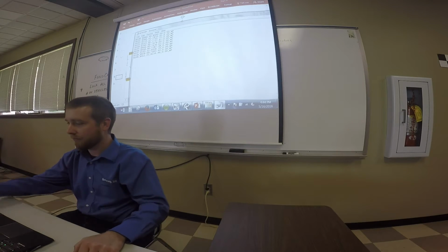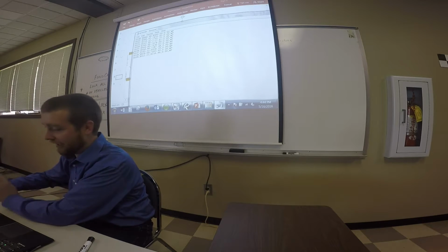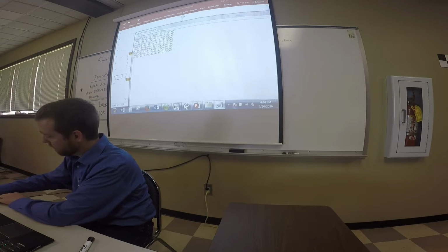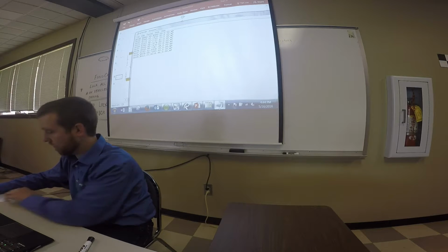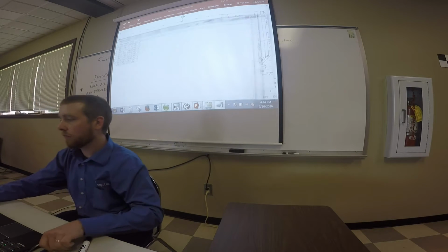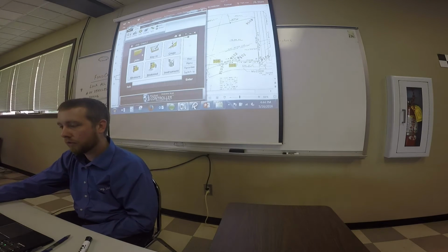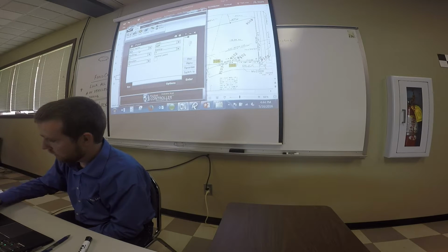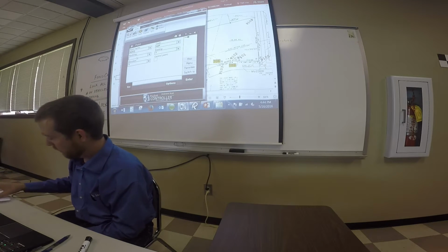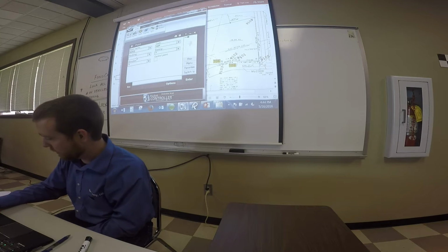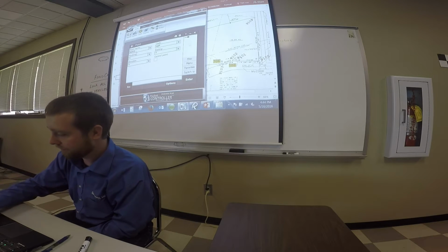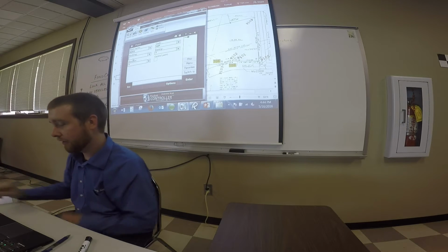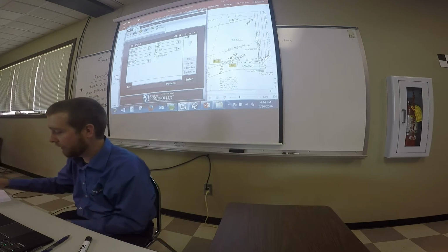And the reason you can enter just one is because he hasn't done a rotation. I have not done a rotation yet. It's just a plain translation. So you can use that one point to get that same translation. So you move it first, rotate it second? Correct. All right, we're going to rekey in the point 9101. We'll call it 9102. This is just so we can have a starting point to move this other one that I messed up.